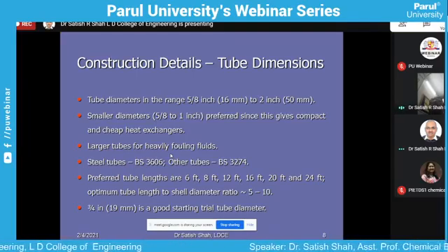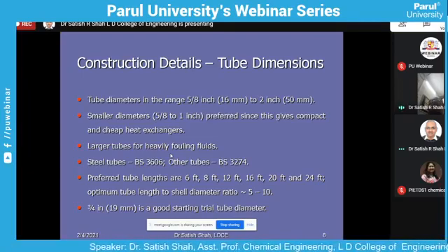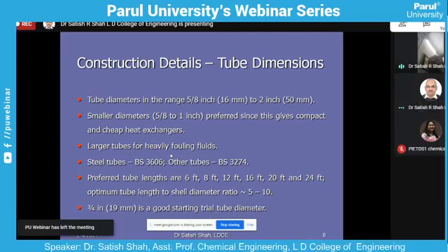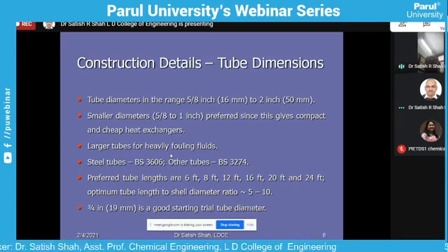So we have to use both. But nowadays metric is available. Sometimes I will tell you that you will be using a 6 feet tube. Immediately you will convert this 6 feet into mm, and the figure you get will not match our normal 2000 mm or 1500 mm or 4000 mm metric length. But it is available.